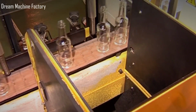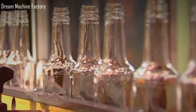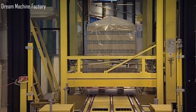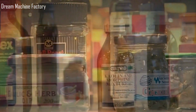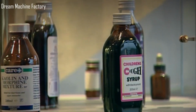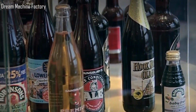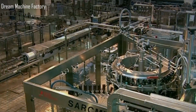The first test checks whether the bottle's mouth, the opening where the cap will later be fitted, is the correct size. Any deviation could cause sealing problems during filling. After this, the bottles move into the inspection chamber, a brightly lit area where high-speed cameras scan each bottle for cracks, bubbles, or deformities that could compromise safety or quality. Those that fail are immediately rejected, crushed, and sent back to the furnace as cullet for recycling. The bottles that pass inspection are stacked, packed, and prepared for delivery.